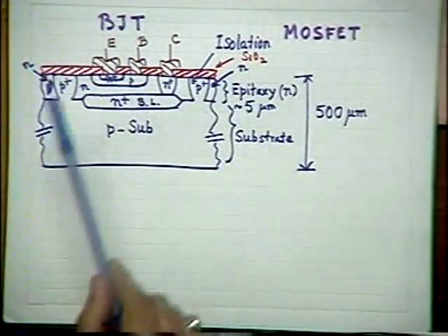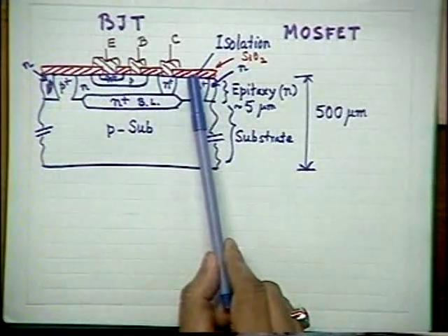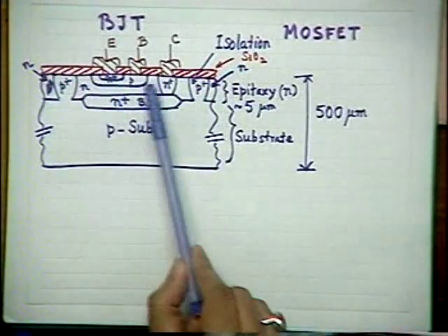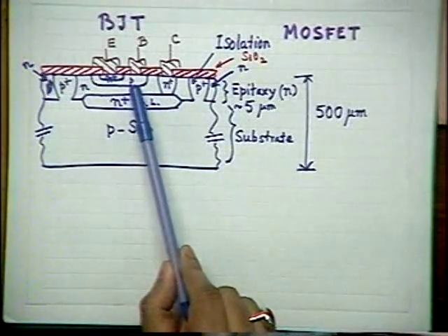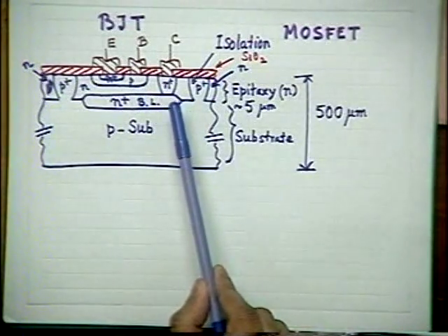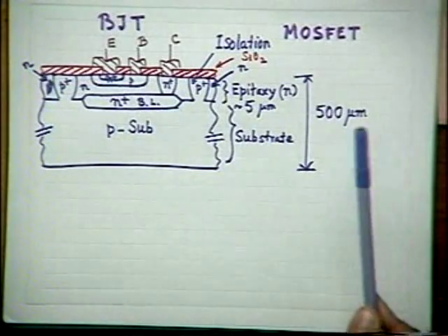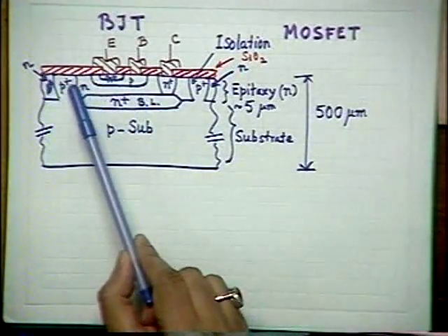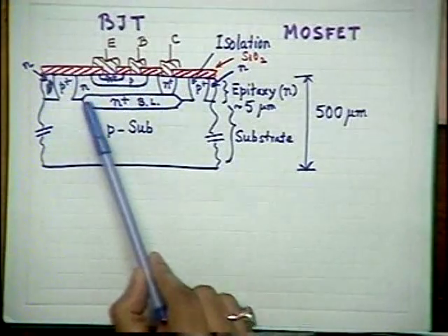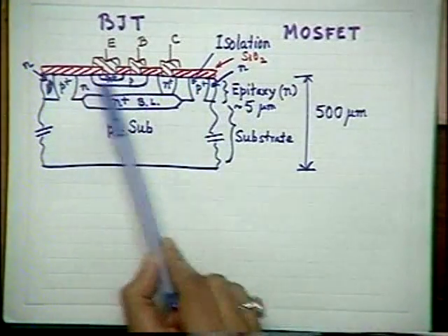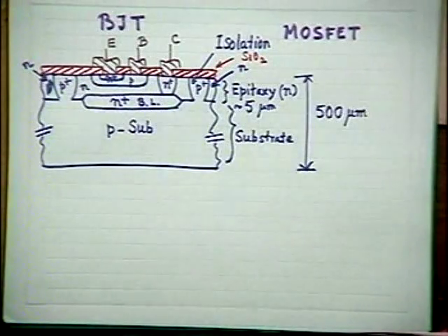And this passivation or oxidation can be used as a mask for selective doping or selective junction formations, which are so important for the realization of a transistor or a diode. So you see that you are doping first only up to this region, or this region, selectively. And that was possible because we have grown a very nice quality oxide.